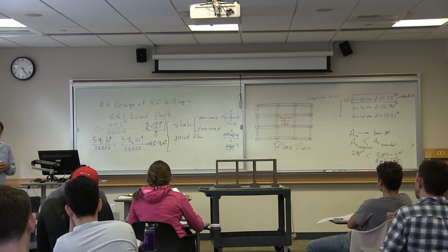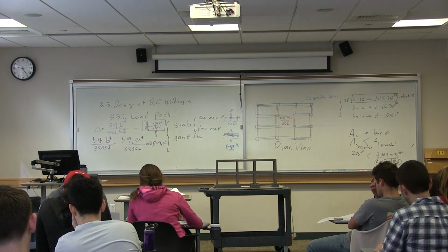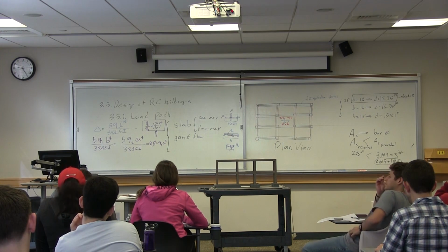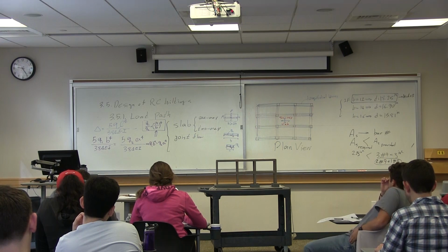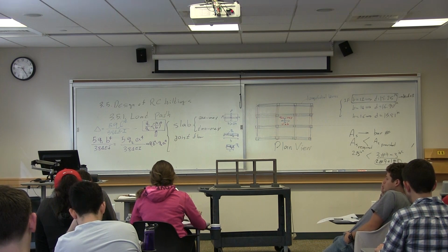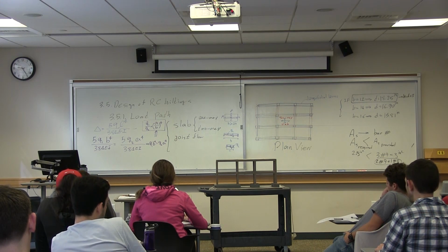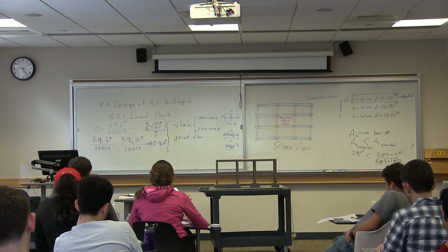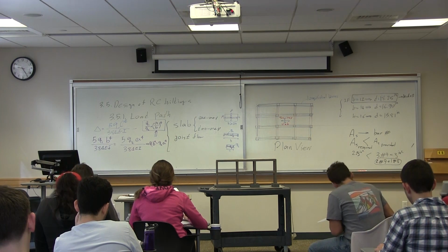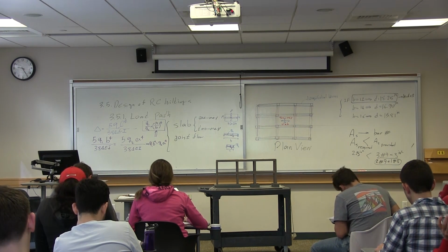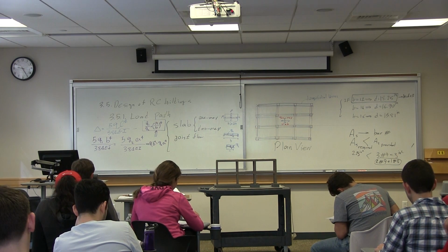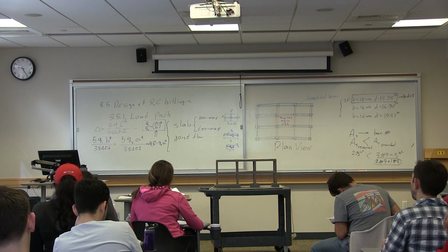Let me ask you this. If you did not know this and you wanted to analyze that frame, can you analyze that frame? The answer is no, because you don't know what the loads are. First, you have to identify where the loads go, then you model it and analyze it. Does everybody agree that without understanding the load paths, you would not be able to analyze those frames?